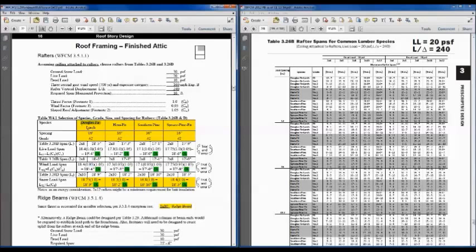But let's look at a Doug fir larch, 16-inch on center, number 2 grade rafter span, so we're going to jump into this rafter span table here, 326B. 16 inches on center is our spacing, and we're Doug fir larch up here, number 2, and we're moving across. We need a 16-foot span, so a 2x6 won't quite work. That's only 14'4", so let's look for this one, which was 18'11", and whoops, sorry, 18'5". I was in the wrong row there. 18'5" for number 2 grade. And we see that matches up with what we've selected here in our table.